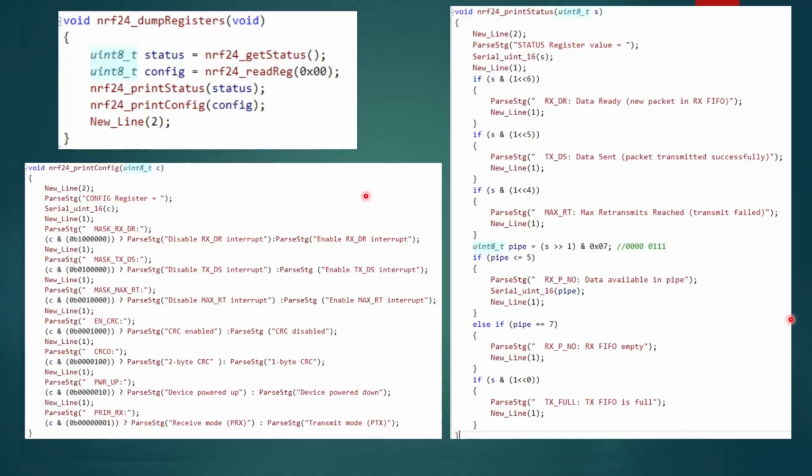And if everything adds up correctly, there is no mismatch, and the receiver and transmitter have been set up, then I will start looking outside: is there any interference that is creating this issue? But the first thing I have to do is make sure that everything adds up here.